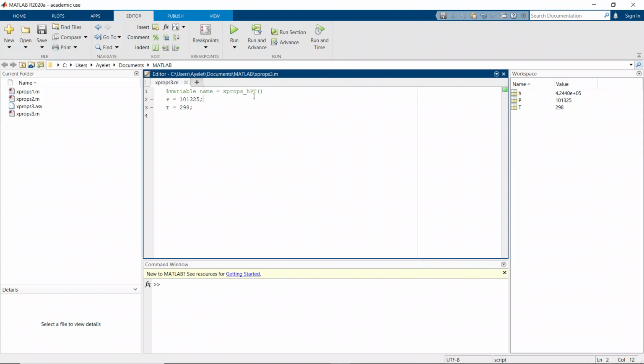The HPT function, as already mentioned, takes in a pressure and a temperature as input parameters, in addition to a refrigerant name. Its output is a specific enthalpy, so we will give it the variable name of H. Then, we will type the function exactly as indicated in the line above and add the first of the parentheses. Once we do that, we should see a small pop-up with the function name and the parentheses with the proper input parameters filled in.